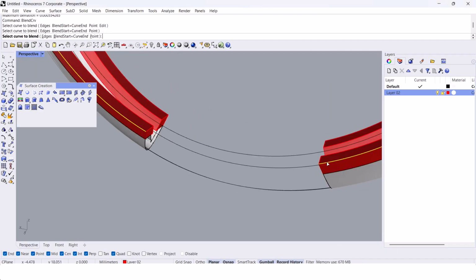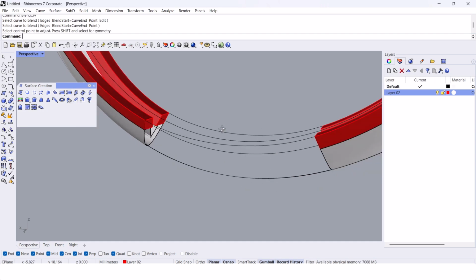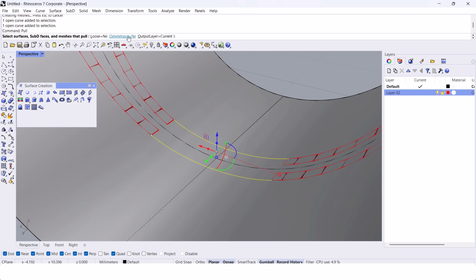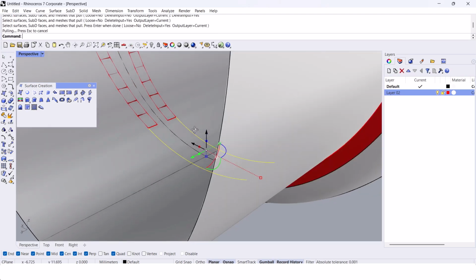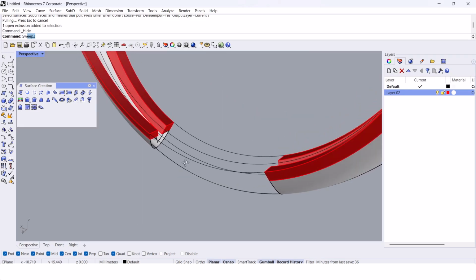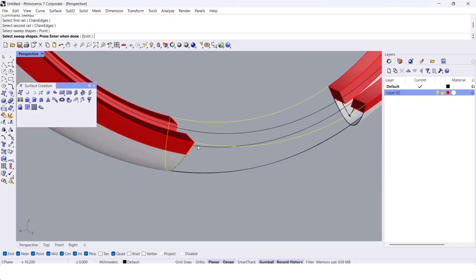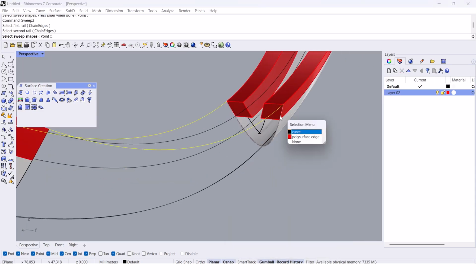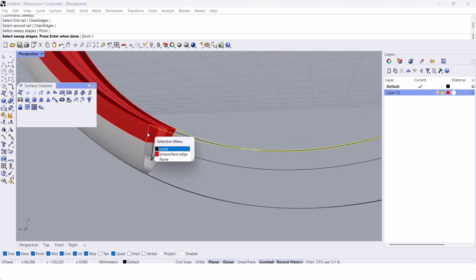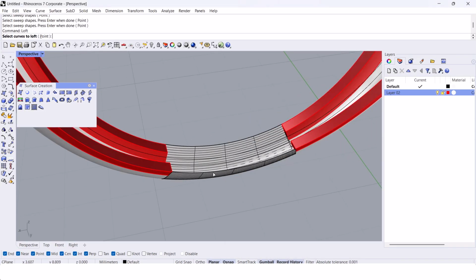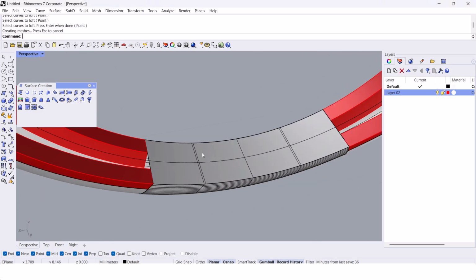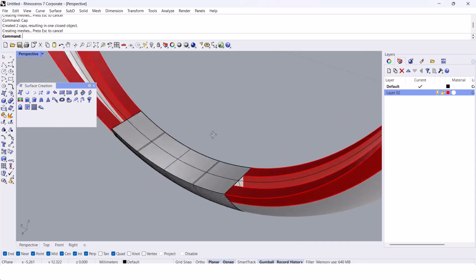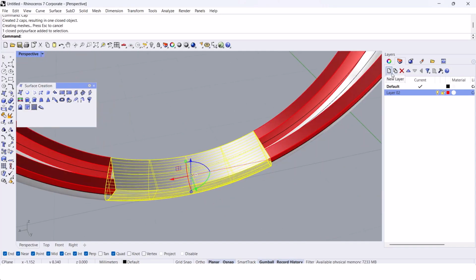Again, blend curve, extrude, do the pull. This time I'm going to delete input because it's a very simple shape. I don't double check it. Sweep 2. Sorry, I selected the wrong curve for sweep. Do the loft. Join, cap. Make sure your poly surface is closed.